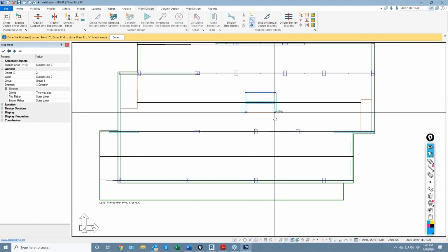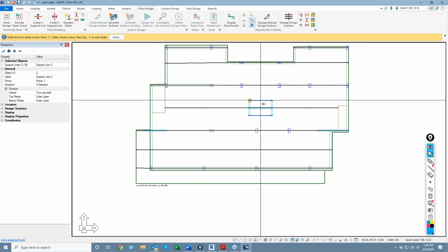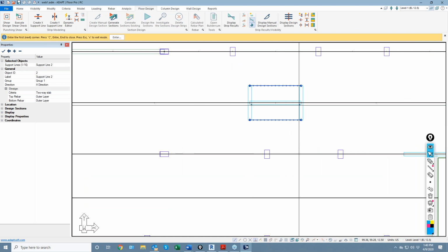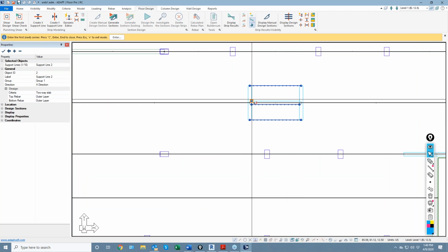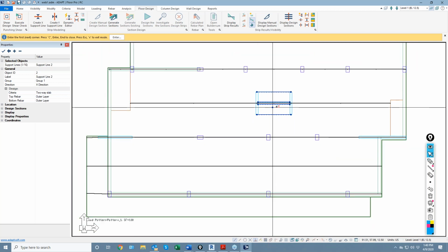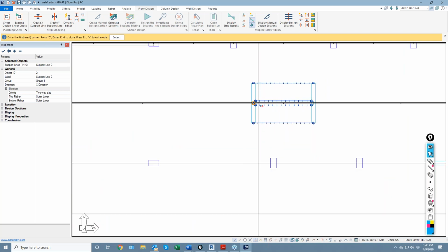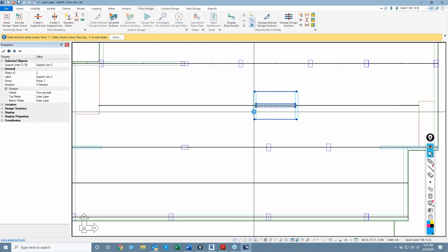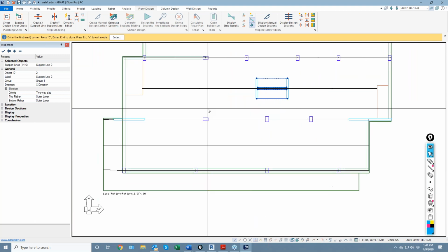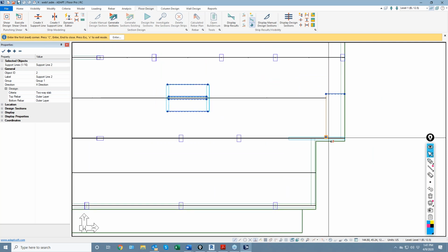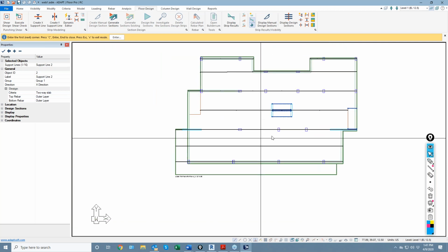So that's fine. We'll go ahead and add some boundaries. The program will stop the section at that boundary. Even like here, if I create that boundary and this boundary, now there will be no cuts that extend through from this inner support line. I likely wouldn't actually add that support line in between there. It's just the slab over the top of a wall. But for sake of efficiency in the meeting, I went through that location. So here we're going to add a splitter, and then again a splitter there.